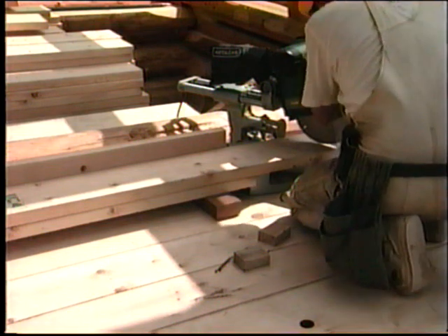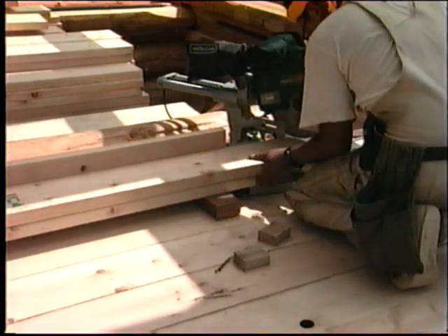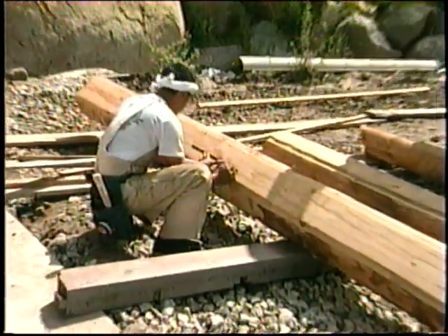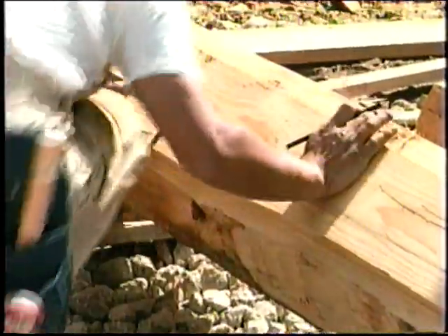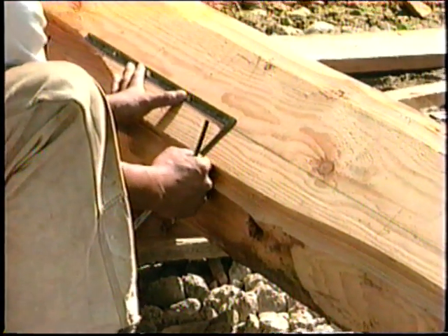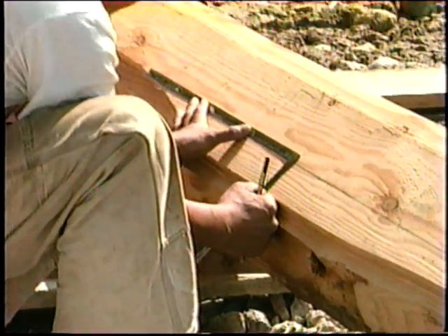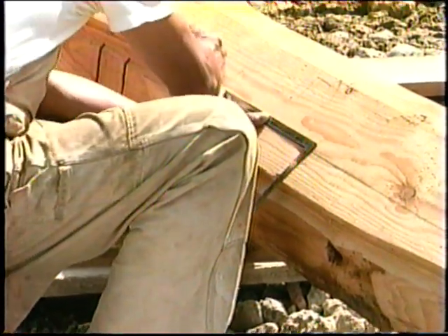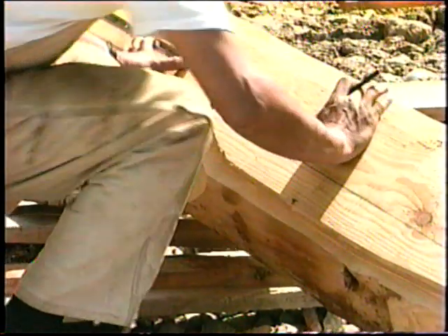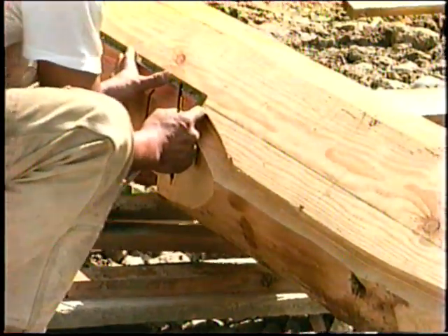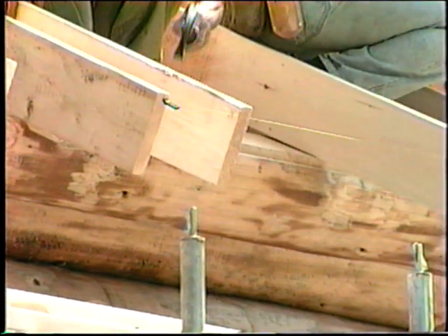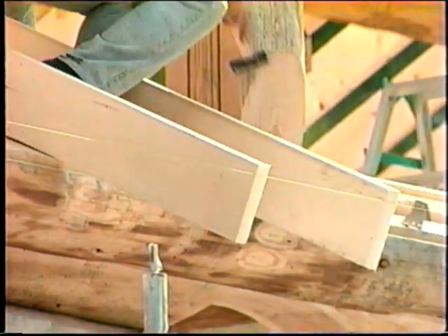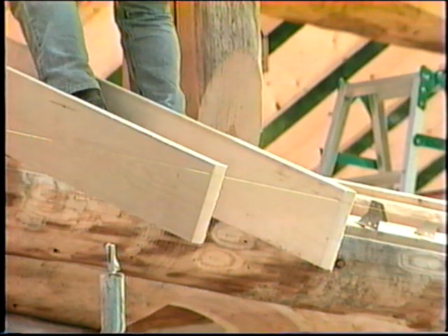These rafters should be pre-cut, and the work will be easier if the rafter positions are marked on the beams before the ridge and purlins are hoisted onto the building. Leave the lower end of the rafter a little long so that it can be trimmed after all the rafters are in place. This will make a straighter eave line.